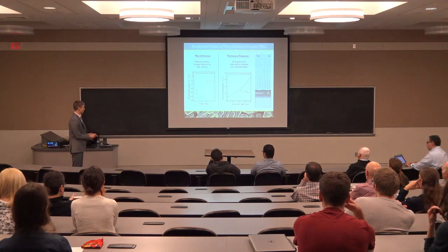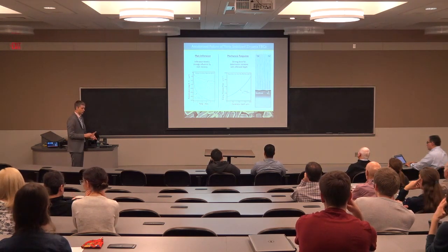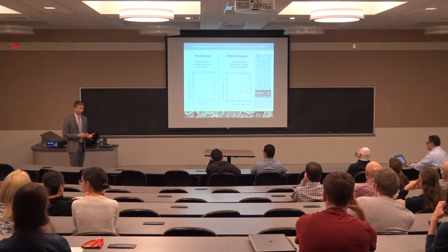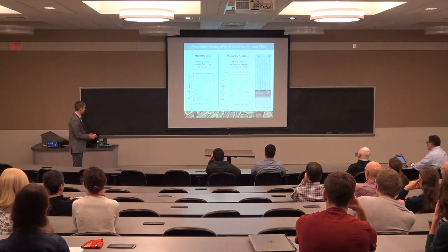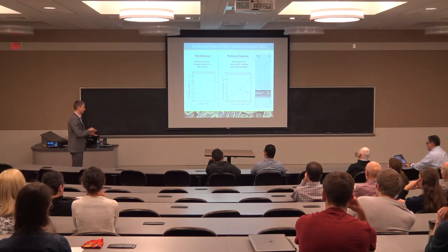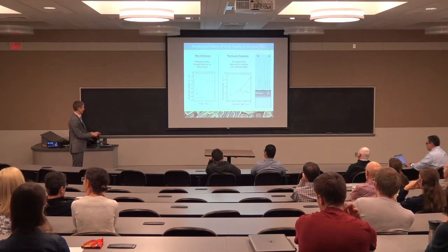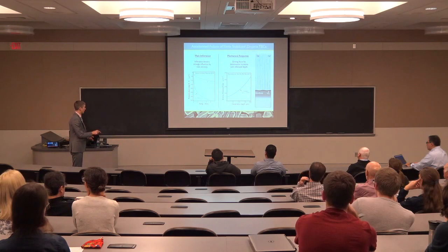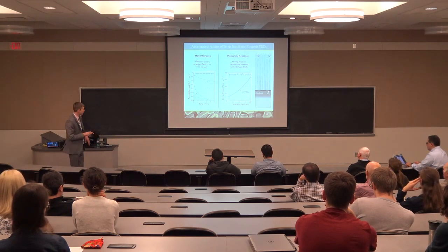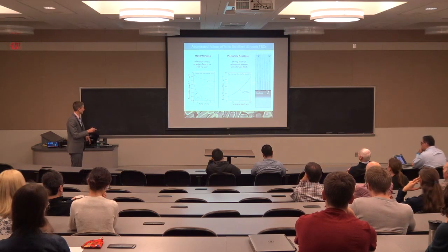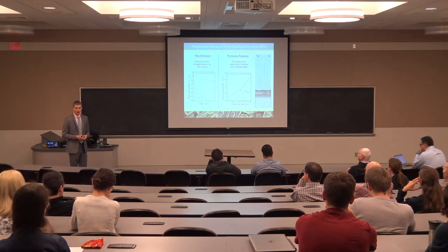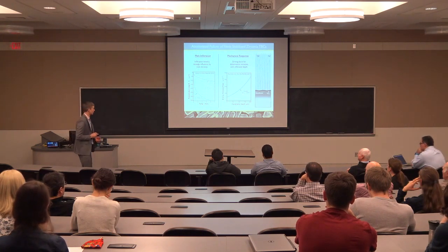And as it penetrates, if we look at the energy release rate, this is the stored elastic strain energy in the coating as the melt penetrates, or after cooling of a penetrated coating, that this energy increases pretty dramatically with the penetration time. It's more than a linear increase. And the toughness of these coatings, depending on the exact microstructure, probably falls somewhere in here, which is to say if we penetrate more than about 100 microns or so, the coating will fall off upon a subsequent thermal cycle.